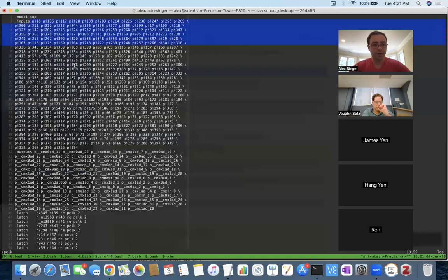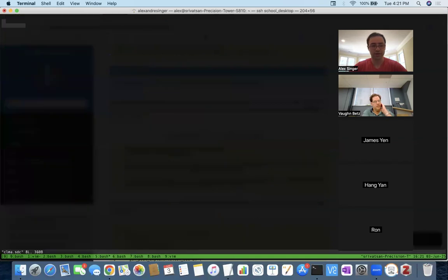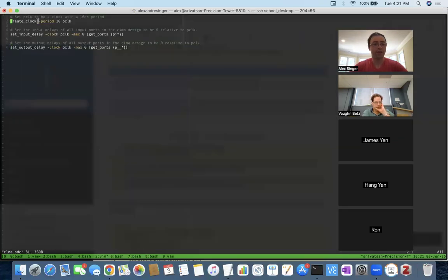And all of these other signals, we're going to assume that they're only going to change at the very first rise, and that's the only time. That's what this max delay is trying to say. It says that when this clock first rises, we're going to say that these ones are not changing before that point or after that point. It's just a way of making sure these have correct timing information.